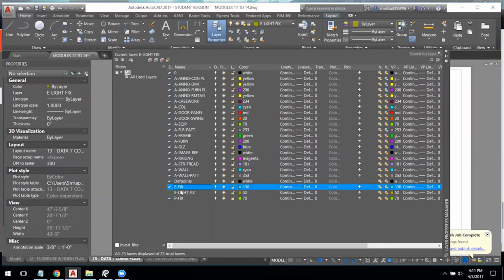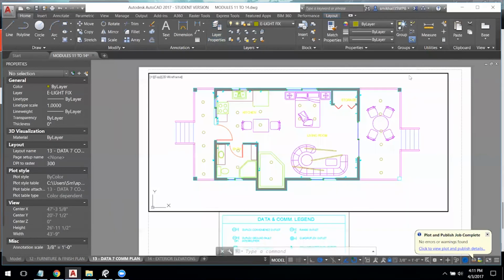which layers you're selecting to edit the line weights, because you could make a very honest mistake like what I just did here. So I'm going to go back again and go to layer 50, color 52, that's the light fixture, make it thin and dashed, and then I'll go to the 130 for the electrical devices and see what color that is. Okay, 130 and 52.